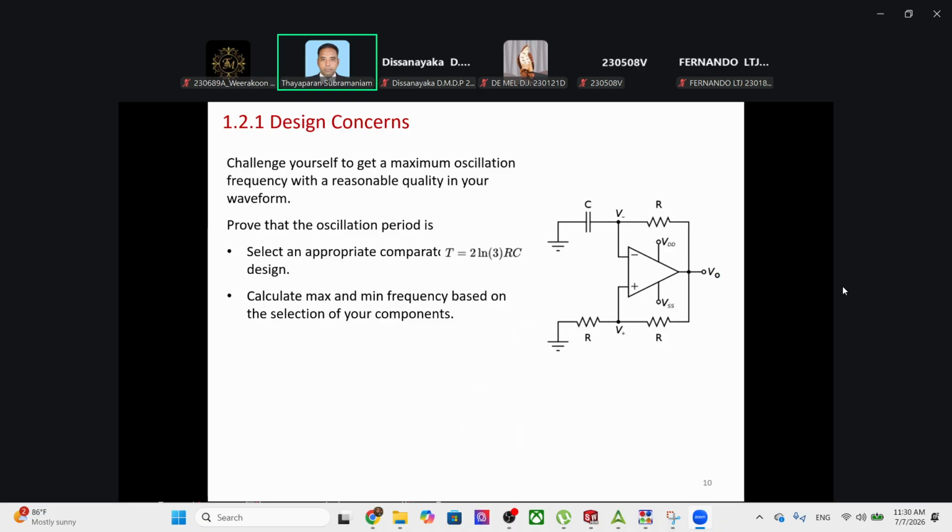No harm, you can go for 1 microamp, because 1 microamp into 5 volt is anyway 5 microvolt, which is negligible power consumption. You have to have the right justification. I'm just estimating. So, selecting this resistance, there can be some deviation.